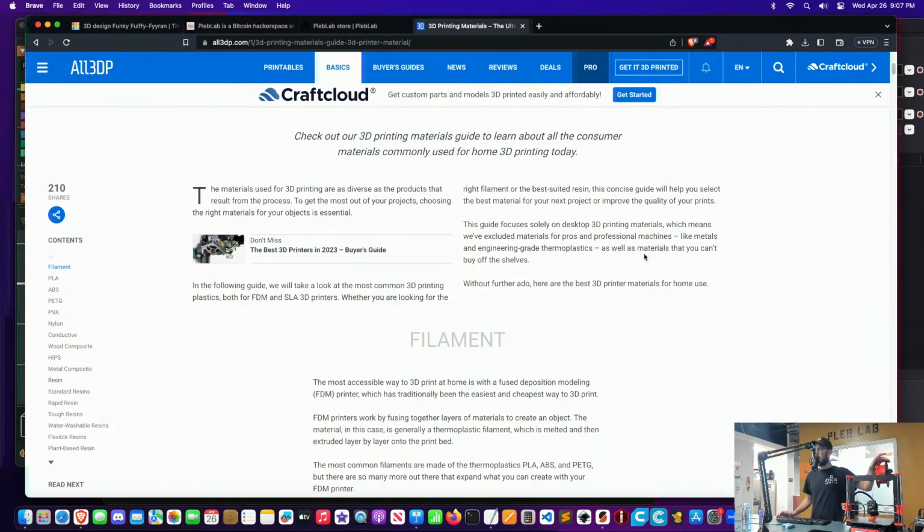PETG is higher, but again, it's around that 100, 120 or so. But your common materials are PLA, PETG, TPU, TPE, that's the rubbery stuff. Basically, PETG is this plastic bottle. I think milk jugs is actually HIPS, but it's your water bottles basically, your plastic Ziploc bags and stuff like that, just with added glycol, that's the G. But it's the same thing, a little bit harder.